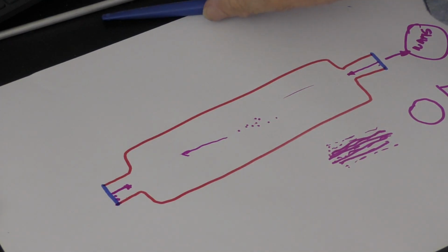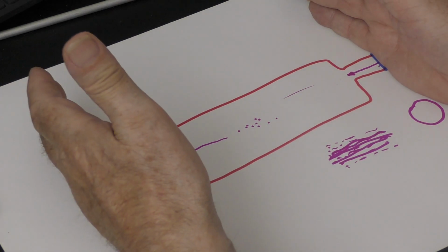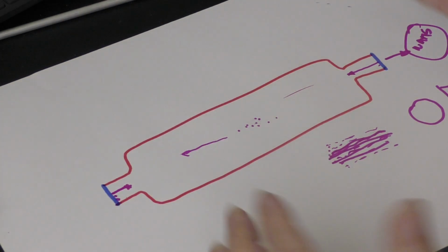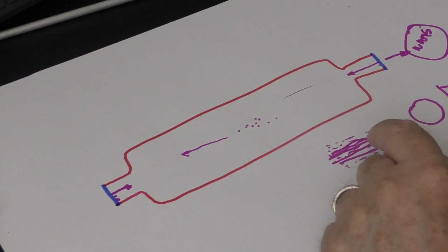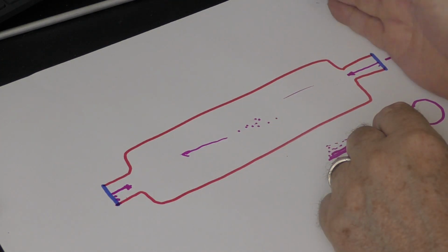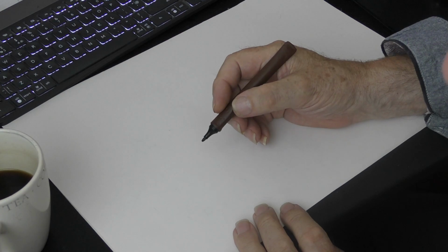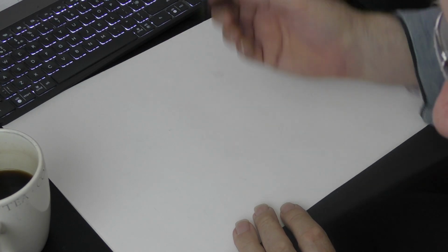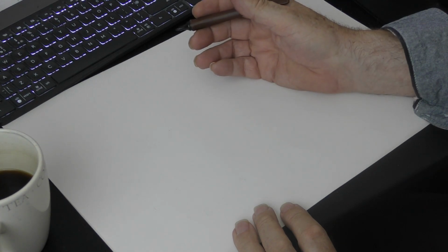One of the major things that happens is this process is very, very sensitive, as you can see. And if something does not quite work out right, the only time they're going to know is when they put these to final test. They'll put a special test current through it and they expect a certain peak wattage out of this tube. So the tube fails to deliver its maximum power at test. What does that mean? Well, it means it's a B-grade tube, as I call it.